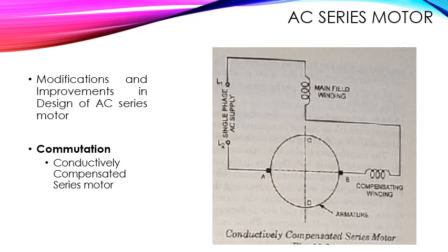The third one is, reduction in the number of turns on the field winding would also reduce the flux for a given current and would tend to increase the speed and reduce the torque available for a given current. Hence, to develop the required load torque, the number of armature conductors would have to be increased proportionately.